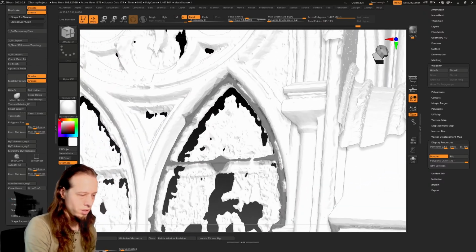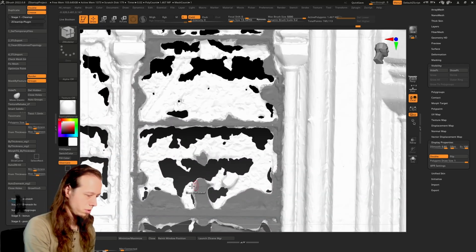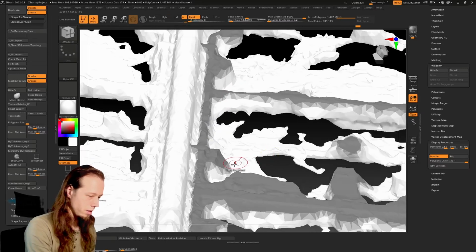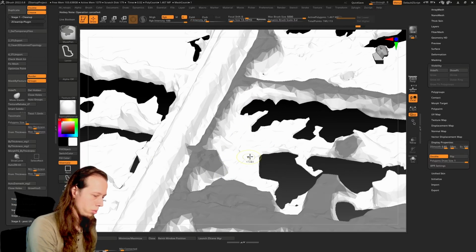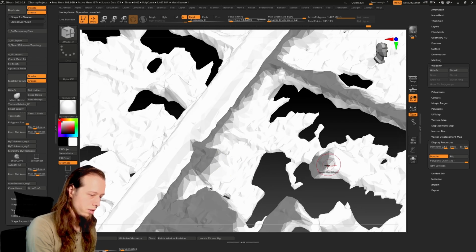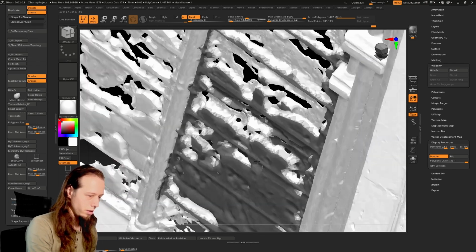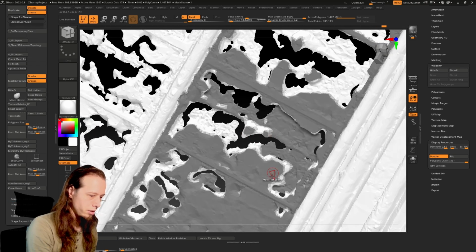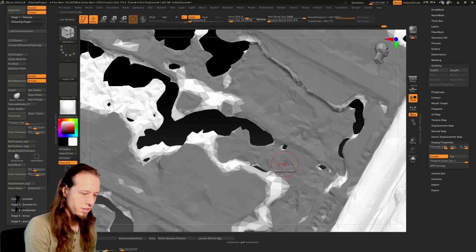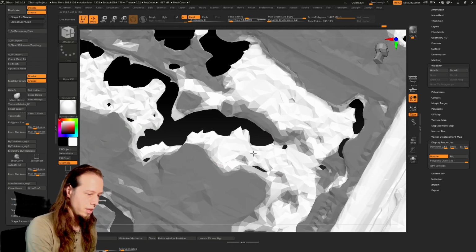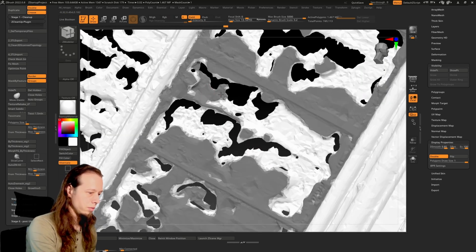So right now I can see that ZBrush makes quite a good selection right away, with almost most of the polygons. Up here I can see there's some of those that I don't want. So with the lasso tool I can quickly deselect them, add that one, and let's see what else up here and here. Definitely we don't want that plane, because it's a stained glass window. So once again, Alt, drag out, same here.